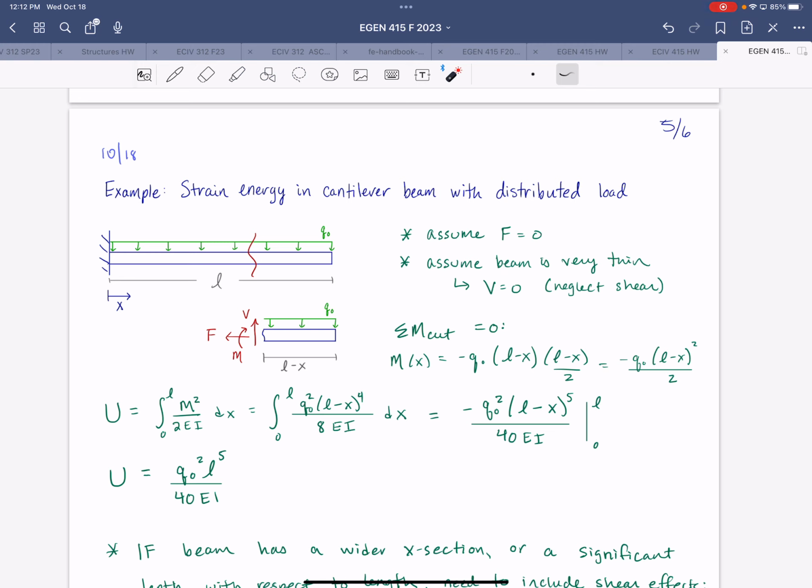And this concept, we're looking at it on the scale of a beam, but it can also be applied to a larger scale, like tall buildings, for example. Very tall buildings tend to behave more like cantilever beams under lateral excitations like wind. So when they are swaying back and forth, if they're very tall, such as the Burj Khalifa in Dubai, the current tallest building in the world, when it deflects, its first mode shape is essentially a pure cantilever.